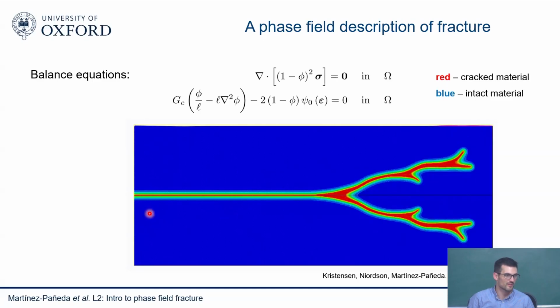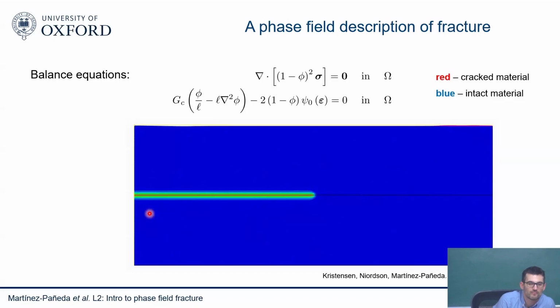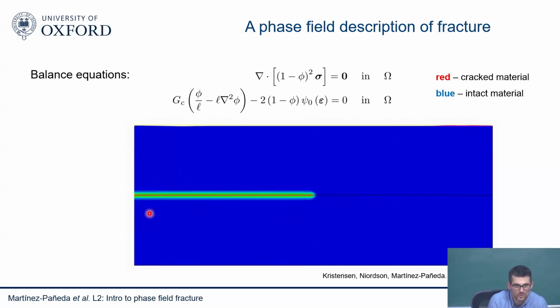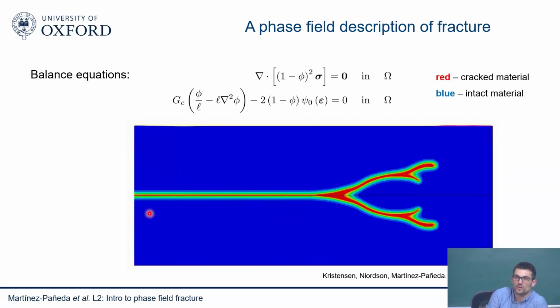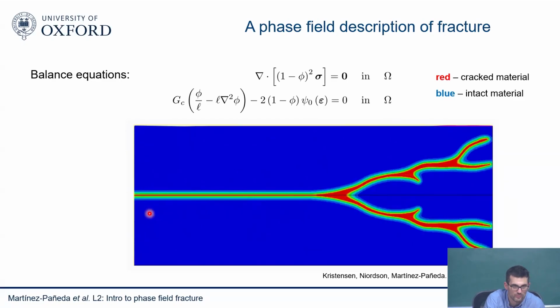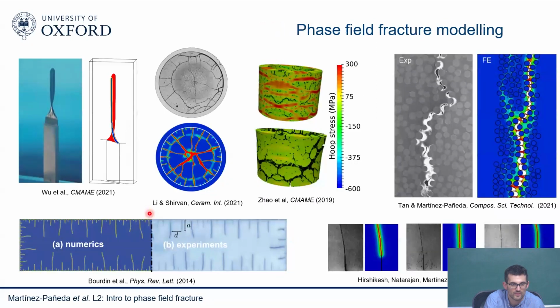Yeah. So if I'm doing a simulation on a square plate of 1 mm by 1 mm and another simulation, let's say 20 mm by 20 mm, so as long as I maintain the L the same, will I get the same? Yes, there could be situations where some edge effects will happen or things like this, but in principle, yes, that will be the same. So in terms of crack growth and so on, you get the same. Always scale it down. So yes, exactly.